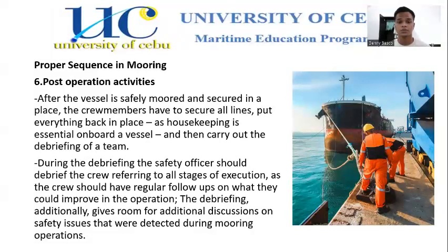So the last is the post-operation activities. After the vessel is safely moored and secured in place, the crew members have to secure all lines, put everything back in place, as housekeeping is essential on board a vessel, and then carry out the debriefing of the team. During the debriefing, the safety officer should debrief the crew, referring to all stages of execution, as the crew should have regular follow-ups on what they could improve in the operation. The debriefing additionally gives room for further discussions on safety issues that were detected during the mooring operation.